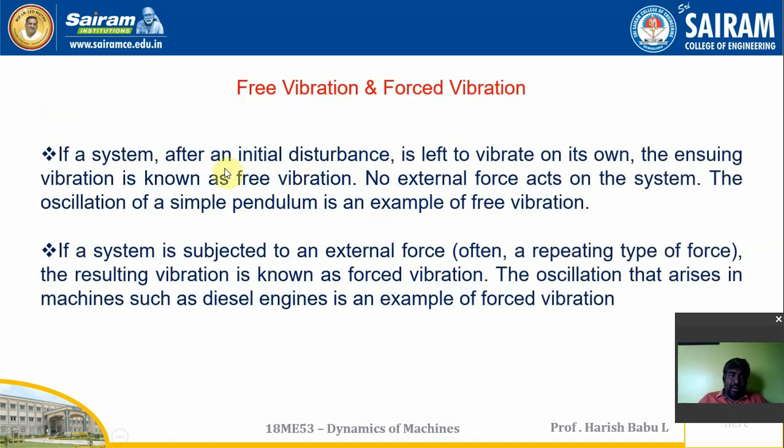If a system, after an initial disturbance, is left to vibrate on its own, the ensuing vibration is known as free vibration. Take a pendulum: you just take the ball to a particular height and drop it. In between you won't apply any force on the ball. The motion will continuously go to and fro, and it is going to stop at a particular time. This type of motion is called a free vibrating system. There is no external force acting on the system. The oscillation of a simple pendulum is an example of free vibration.